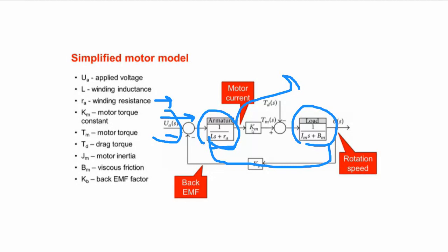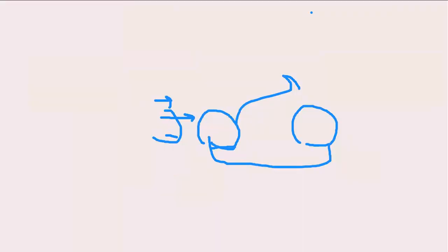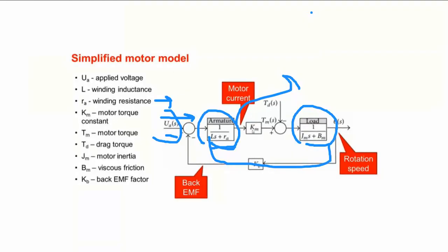Okay. For example, if you use incremental encoder, your motor rotates 1 RPM. It will send you, for example, resolution 2048 pulses per revolution, PPR, for 360 degrees.